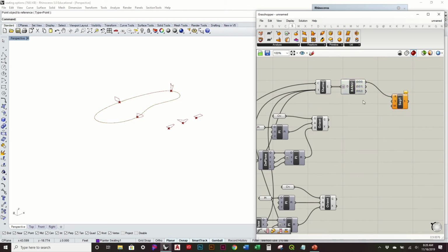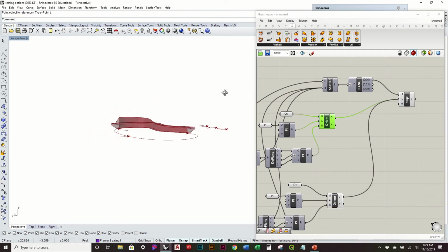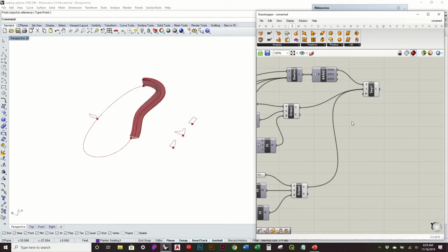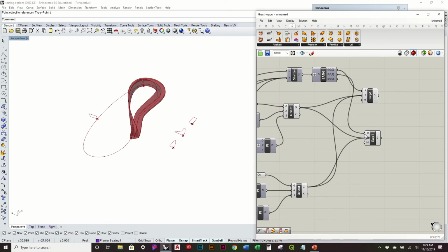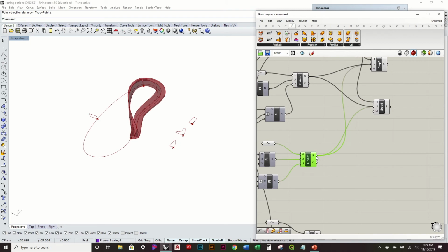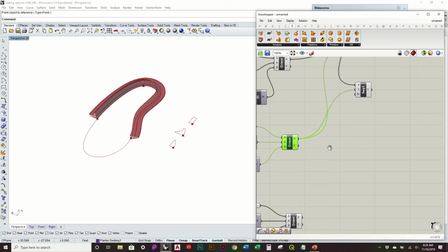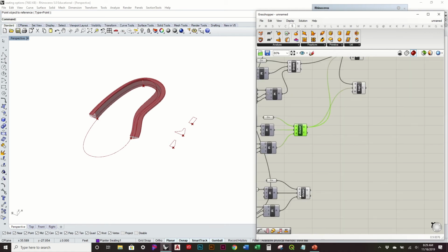Now it's asking for those profile curves, so we can even turn this off. So let's start off with this as our first one, and again, it needs multiple, so I'll hold shift, combine. Now I've got those blending together. So now I'm basically just going to, again, copy and paste this, use the next rail curve. I'll still use this component. So I'm just going to click and drag that so it just keeps that as that. Then I'm going to now include the other one.